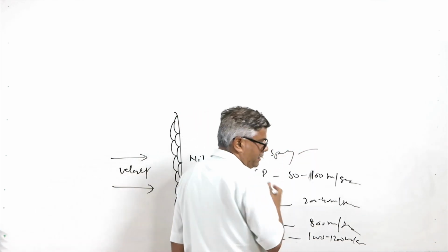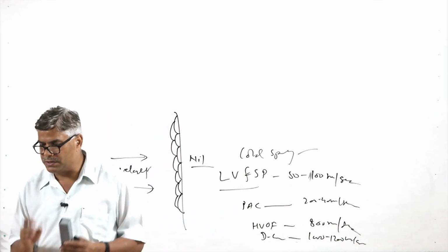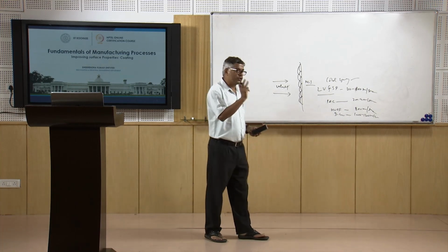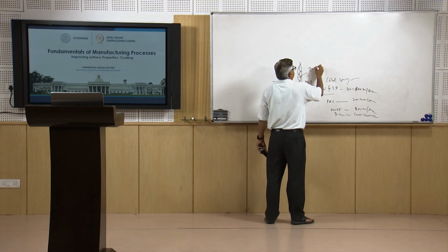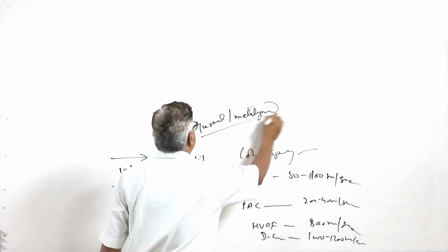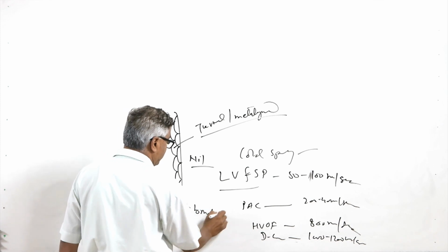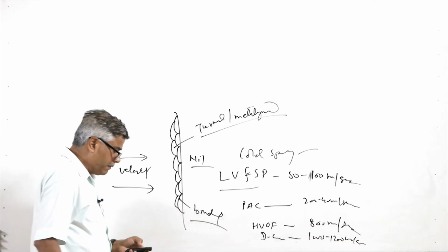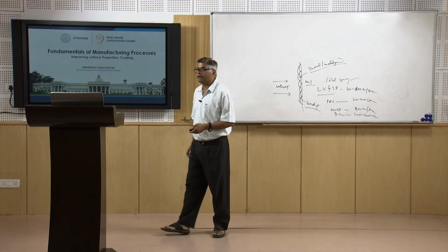As per the process, the peak temperature attained by the material in the course of heating and the velocity attained will vary, and these two things will determine to what extent thermal or metallurgical degradation of the coating material takes place, and how firm the bonding is between the coating material and the substrate. So, it becomes important to see the different kinds of processes and their comparative study.